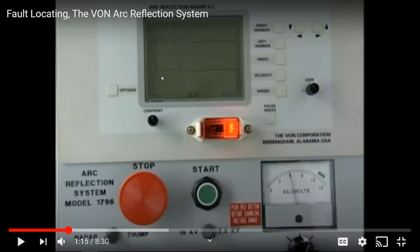It's sending a radar signal down the cable right here, and it shows there's some hash marks. There's one here and one here, one here and one here. It is showing the actual span of primary that you're testing. And down here at the bottom, I can hardly see it, it's going to show you the actual footage right there. Now, on the top, there's a peak that's right here, and there's a valley right here.